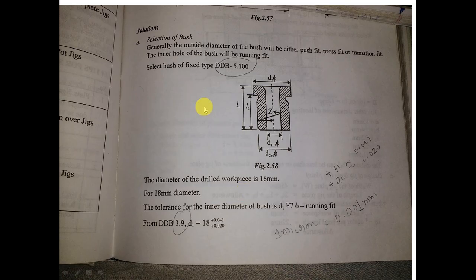So this value L2 is equal to... because the drill bush is going to rest on the top portion of the jig plate in this area. This area here and here represents the jig plates, the width of the jig plate. So the width of the jig plate must be equal to L2 of the bush, because this is going to sit exactly on top of the top portion of the jig body, or on the top plate of the jig body. Hope you're able to understand this.